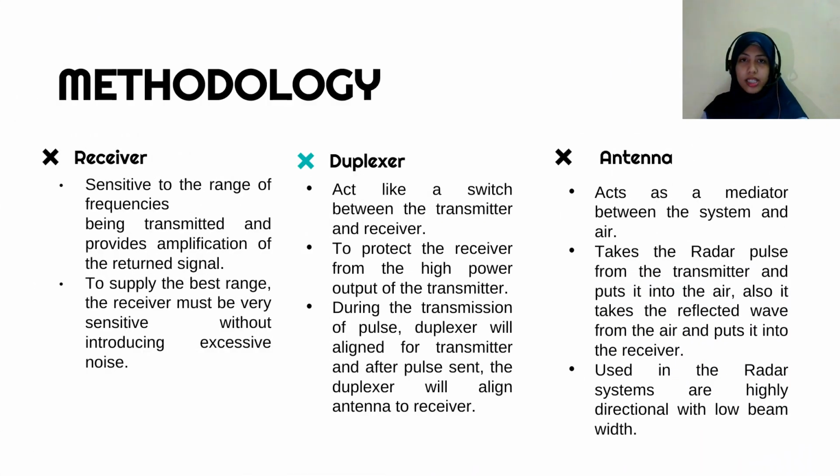The next one is the receiver. The receiver is sensitive to the range of frequencies being transmitted and provides amplification of the return signal. To supply the best range, the receiver must be very sensitive without introducing excessive noise.